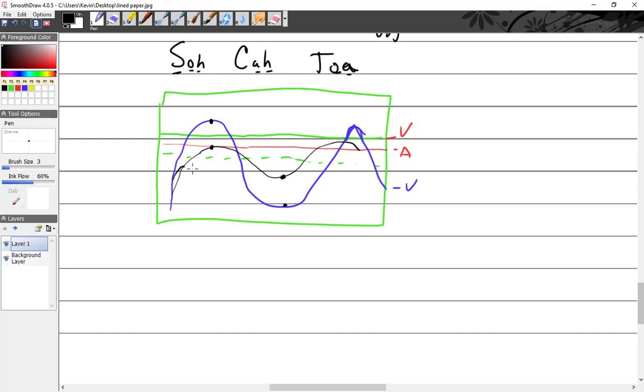So if you were working on, let's say, an aircraft, and you're going to add something, like adding this motor to this AC system, then you would have to figure out what kind of phase shift it is going to cause. That's where we get into AC: we evaluate circuits and determine whether they're in phase or out of phase. So you're talking about phase as in the voltage versus the amps? Yes. On this chart, this is the amps and this is the volts, and they start to spread out. So the peak here is not the peak here.